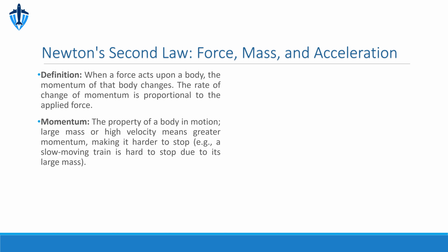Conversely, when considering the speed or distance advantage, we reverse this calculation: 12 divided by 9, resulting in a ratio of 1.33. This tells us that a larger gear driving a smaller gear results in higher rotational speed for the smaller gear, but with less available force. This leads us to a crucial concept: gear reduction.